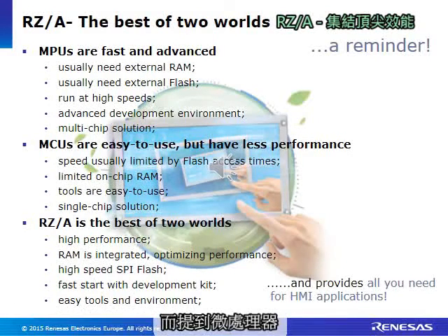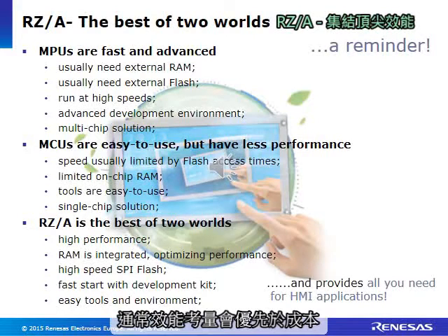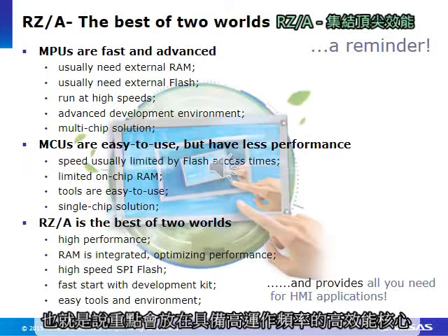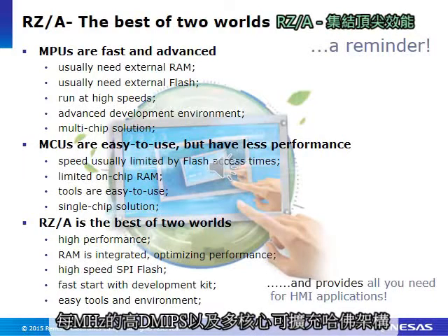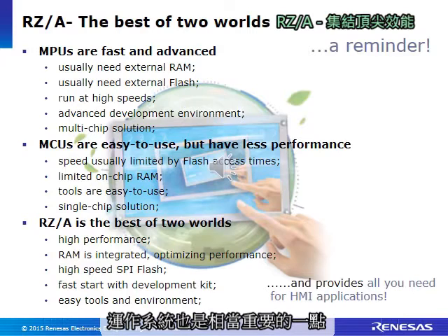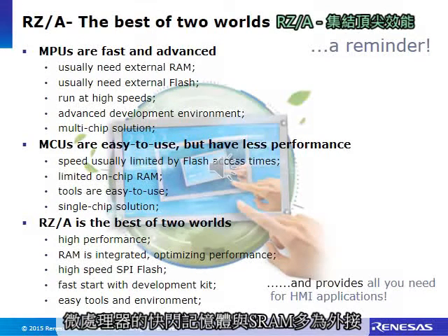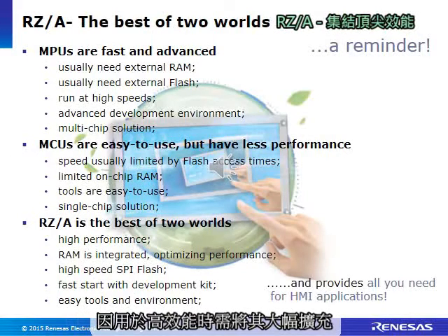As far as microprocessors are concerned, performance is usually more important than cost. This means there is a big focus on high-performance cores with high operating frequencies, high DMIPS per megahertz, and multi-core superscalar Harvard architectures. The operating system is also very high on the list. Flash and SRAM are usually external with microprocessors, as these have to be scaled heavily in high-performance applications.